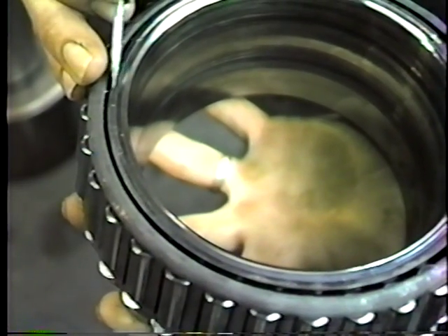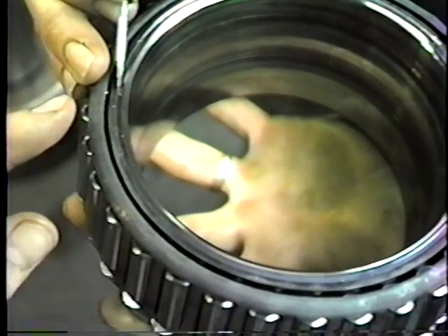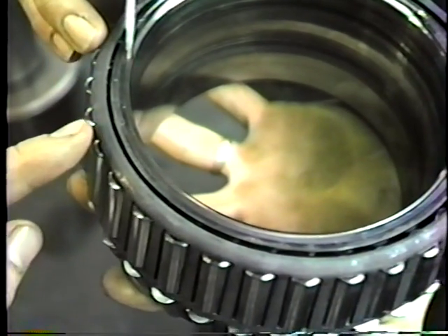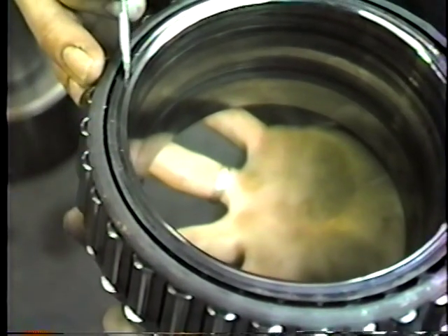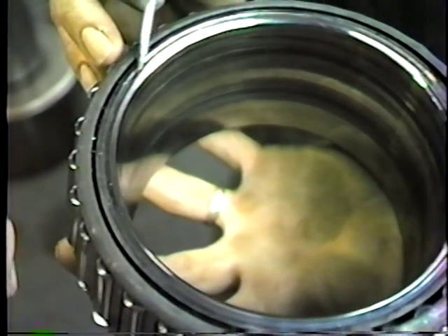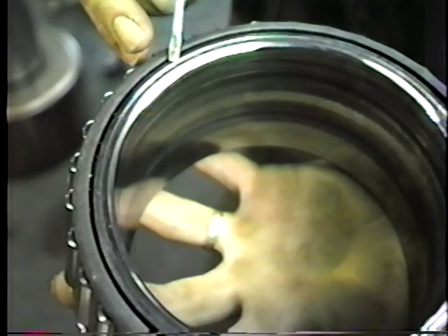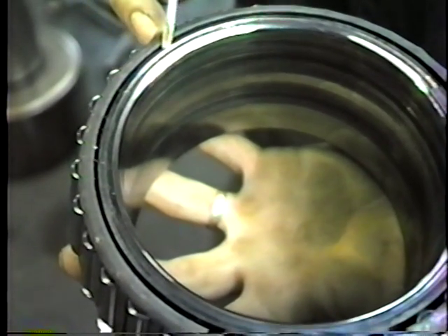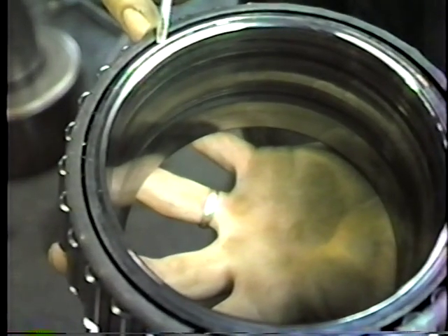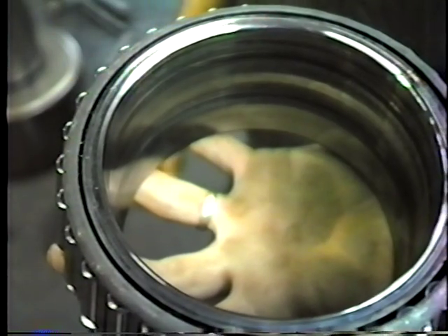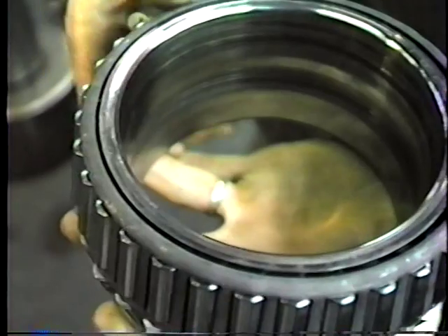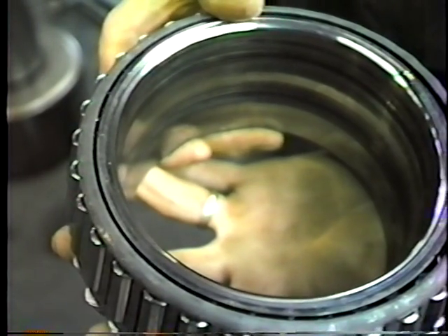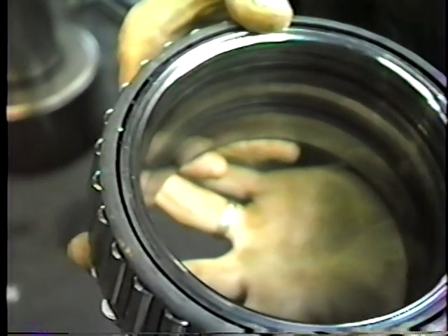This shows some wear where the lower portion of the upper bearing had spun or worn against the shaft of the journal. You can see where it's been indented. There's a corresponding shiny spot on the shaft.